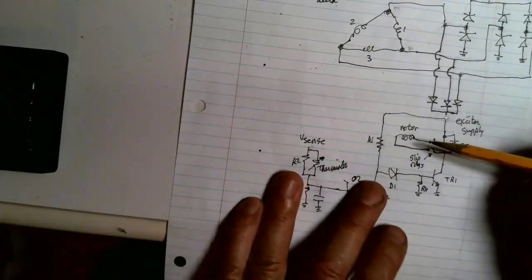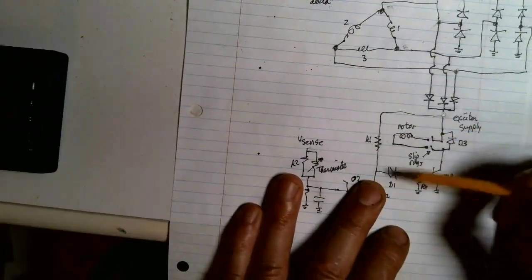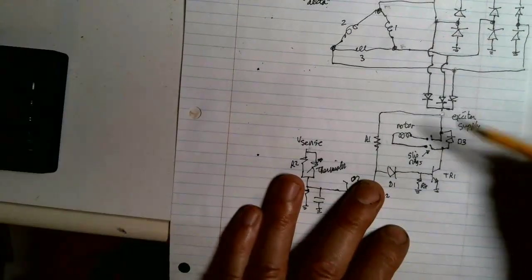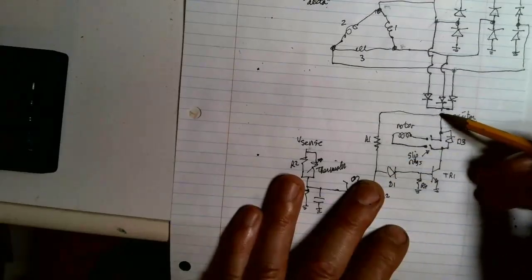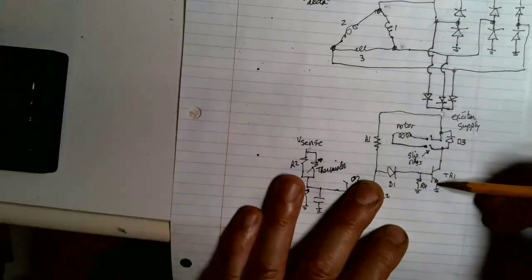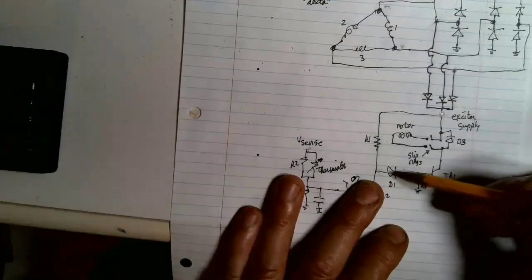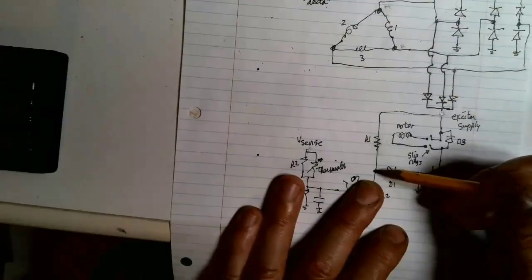This device is off when the alternator output is low, and so this resistor then turns on this transistor here, and so now what is the current that flows? You can figure that out fairly easily. If this is 14.5 volts, because that's what the alternator should be regulating to, about 14.5, then this potential here is 1.4 volts at room temperature. How do I get 1.4 volts? We've got a VBE for this part, that's 0.7, plus a diode drop here, which is 0.7 volts. I'll talk a little later about what this diode's for. So this is going to be 1.4 volts at room temperature.